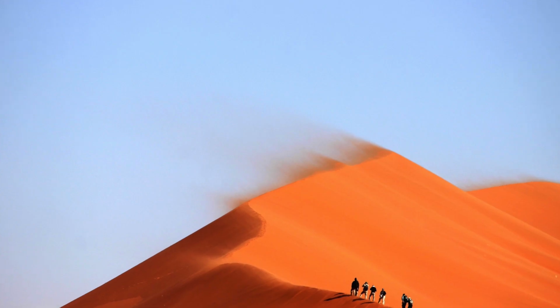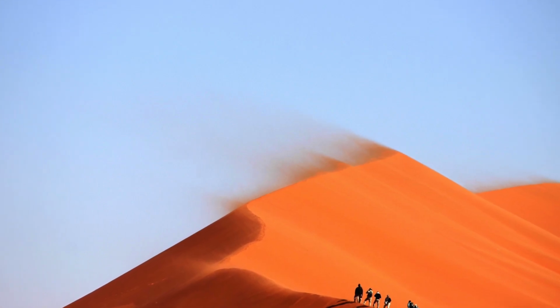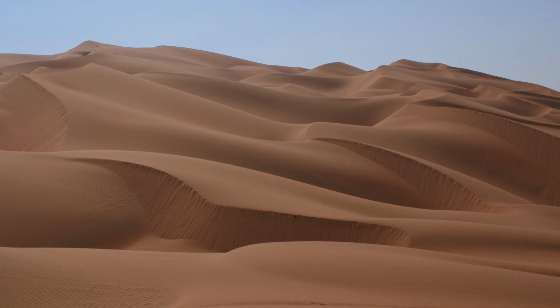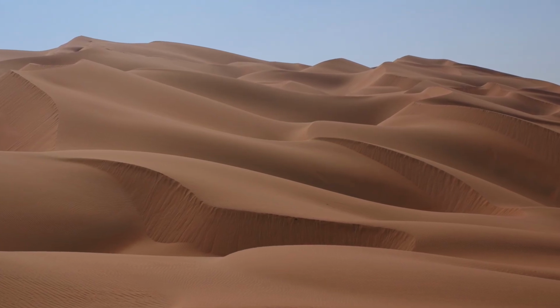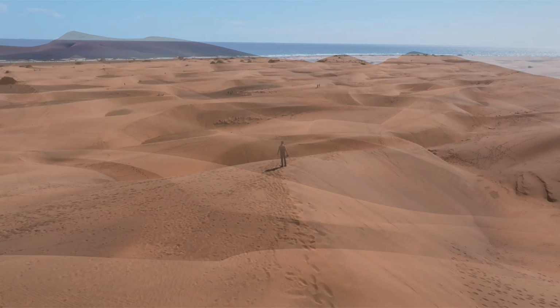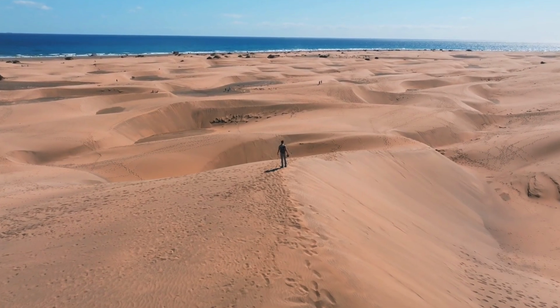Detachment and erosional process. Detachment refers to the separation of soil or sediment particles from the ground surface. It is the first step in wind erosion, and it is initiated when the force exerted by the moving air overcomes the gravitational and cohesive forces holding the particles together. When wind speed reaches a critical threshold velocity, particles begin to vibrate, loosen and eventually lift off. Turbulent eddies and microbursts of air also contribute to particle disturbance.